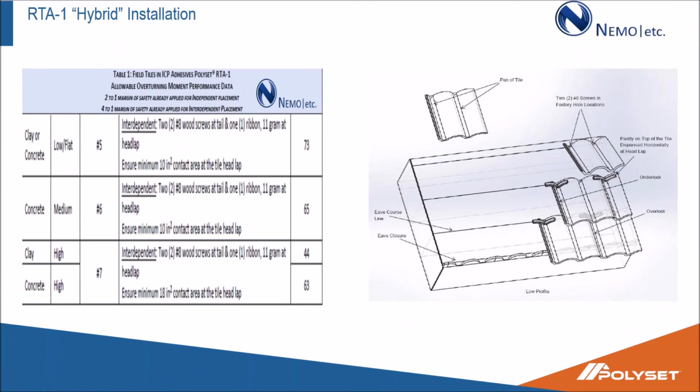With adhesive, you want to make sure that you're using an approved underlayment. These are underlayments that the manufacturer has tested with their adhesive products. They are compatible. Most of them have pretty much the top underlayment products that you see in the markets today. But if by chance you do happen to use an underlayment that's maybe not approved, or you've just been using it for a number of years and that's your go-to product and you still want to use adhesive, you also have what's called a hybrid system, where you can put those two mechanical fasteners on that tile, put a bead of adhesive right on the overlaps of these tiles. And what that's going to do is give you a higher moment uplift number, and it allows you to use your underlayment of choice.